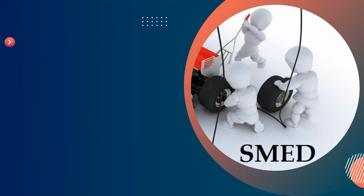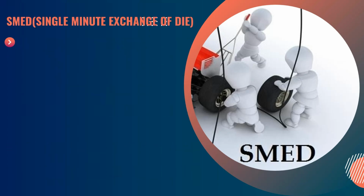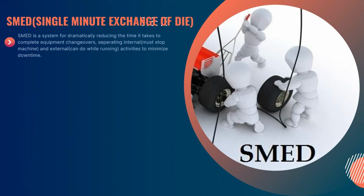Let's go to the next slide and understand about SMED, or single minute exchange of die. SMED is a system for dramatically reducing the time it takes to complete equipment changeovers, separating internal must-stop-machine activities and external can-do-while-running activities to minimize downtime. Let me explain the internal and external activities. Internal ones are those for which you have to stop the machine, and external ones are those which you could do while the machine is running.